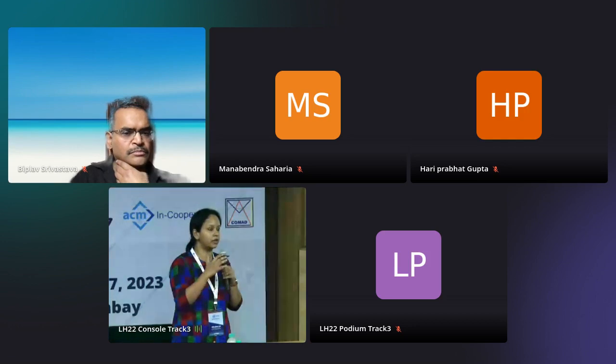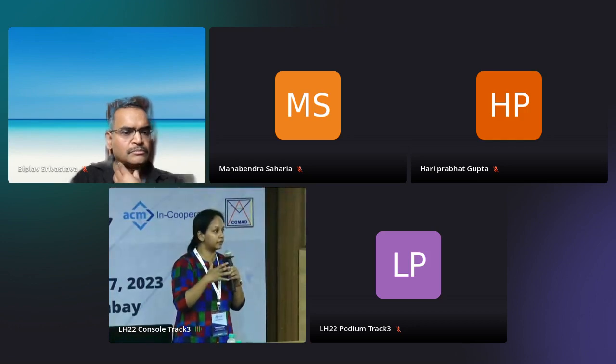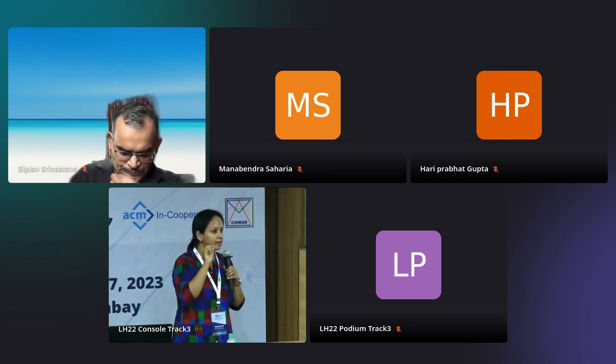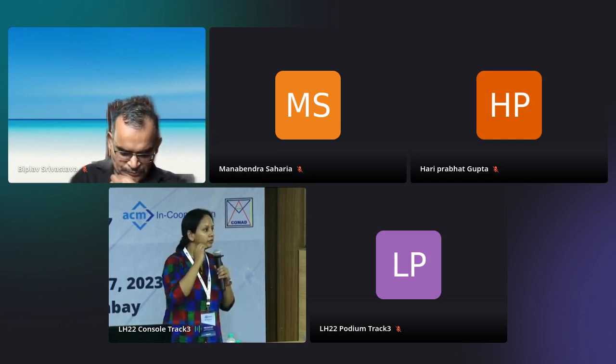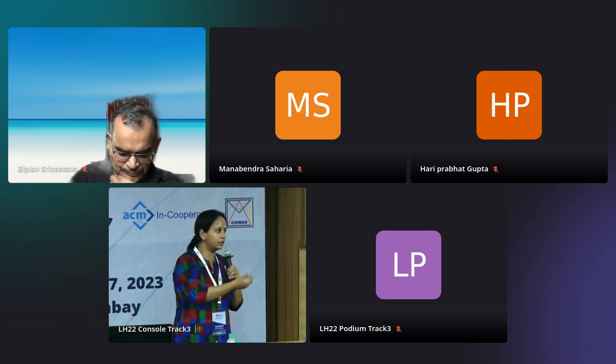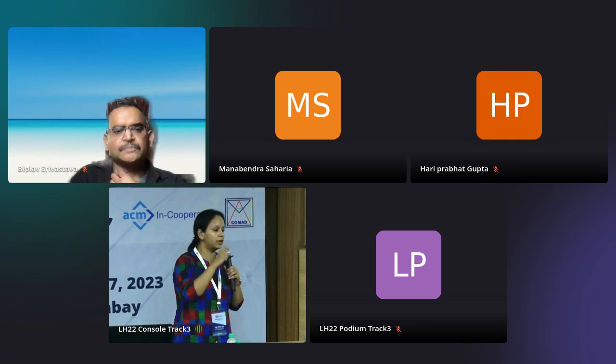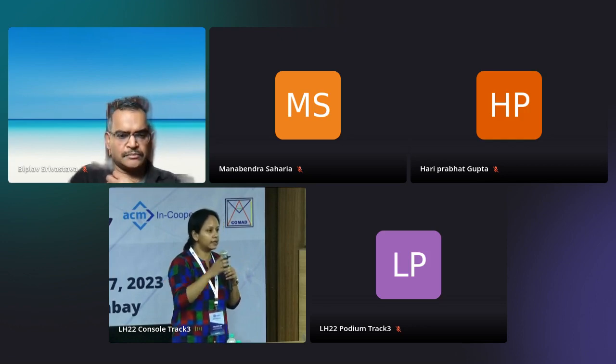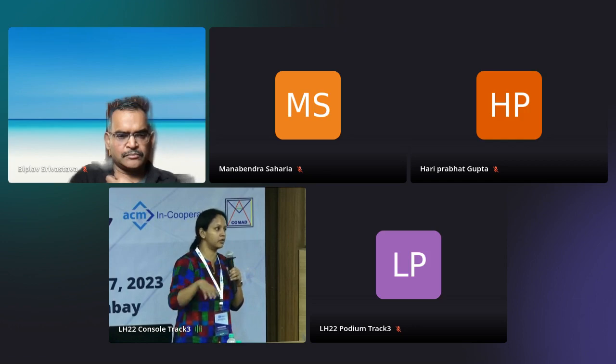So if you are discharging into, let's say, a very sensitive water body, where there are very specific types of aquatic species which are sensitive to slight changes in maybe pH or water quality, you would want a different standard or a different level of treatment. If you are discharging to another water body where these kinds of considerations or constraints are not there, the regulations are different. So this type of what we call water quality based effluent limits, these are something that we see in the US, not so much in India.